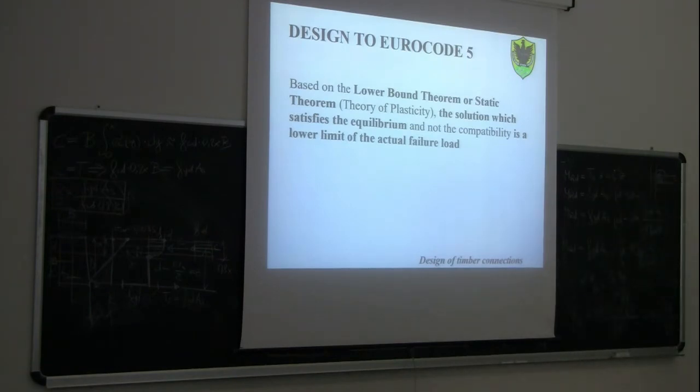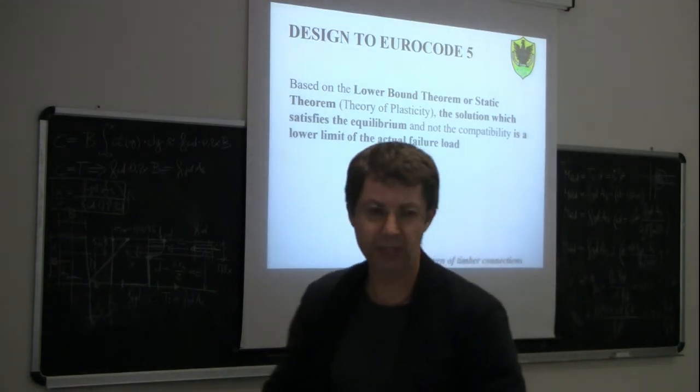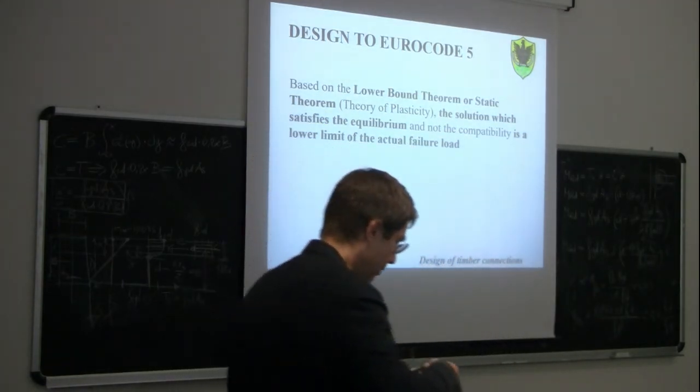In other words, solving the actual problem would be too complex because it would involve both equilibrium and compatibility equations, so we just use equilibrium and find a solution which satisfies equilibrium and not necessarily compatibility.